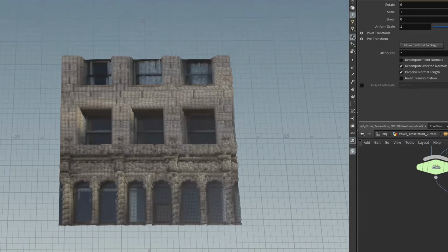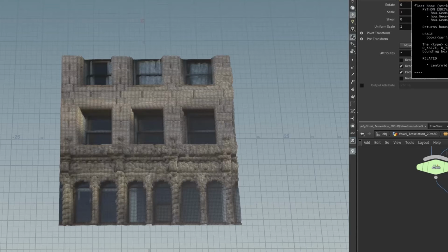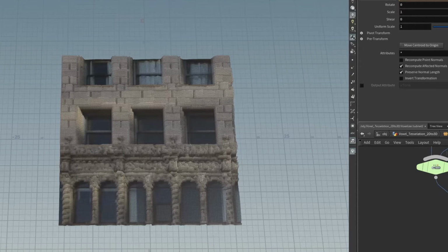So what we're gonna do here is make a bounding box. Like in Rhino, there is a bounding box, but what the bounding box does is that there is a geometry, and you're going to basically cover it up like a gift. So we're going to make this like a gift box. And how do you do that? You use a BBOX, that is short for the bounding box. And we make the bounding box, and then we now have to indicate the directory of that thing.